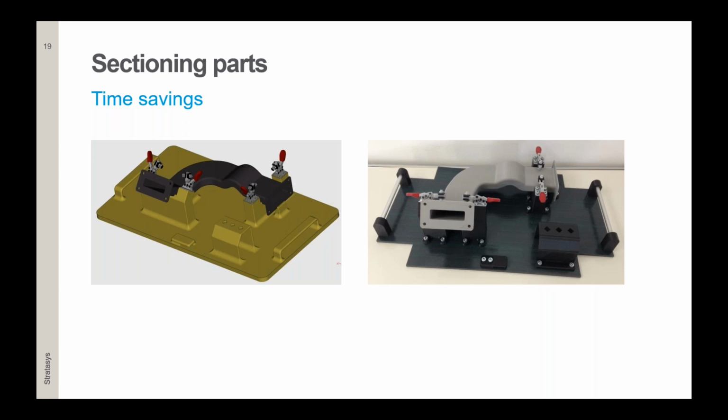Some of the parts you see on the right side have been replaced by metal parts, which can be bought off the shelf, for example the bottom plate, aluminum rods for the handles, and the screws to put everything in place. Printing the bottom plate alone would take almost 9 hours and require around 600 cubic centimeters of material, meaning it would cost around 150 to 200 euros, roughly speaking. And I'm sure you can find something off the shelf to buy for much less.